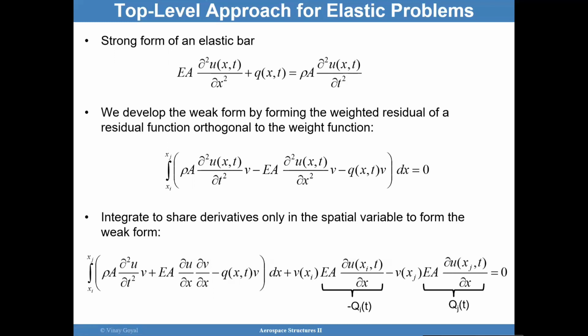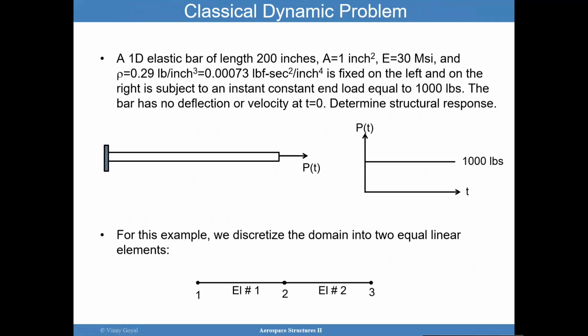What we've done is we've discretized the deflection, which is a continuous variable, into discrete elements. So we discretize its domain into 2 discrete elements, and as a consequence, I've discretized the deflections into 3 nodes, and in between I have an interpolation function or an approximation function of that deflection.